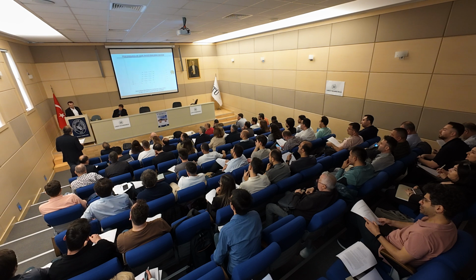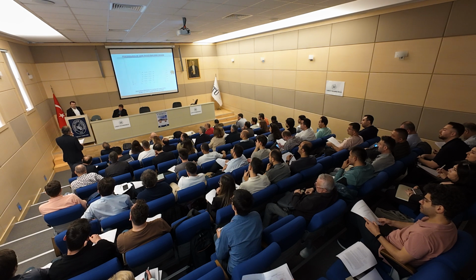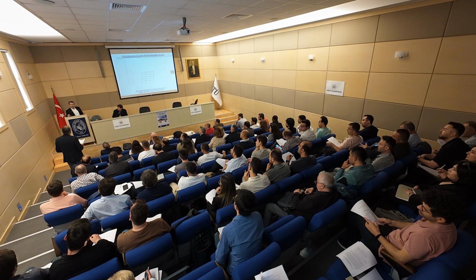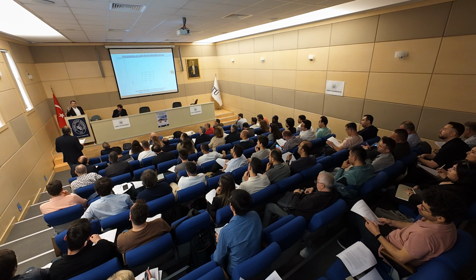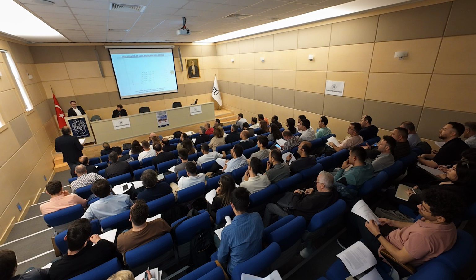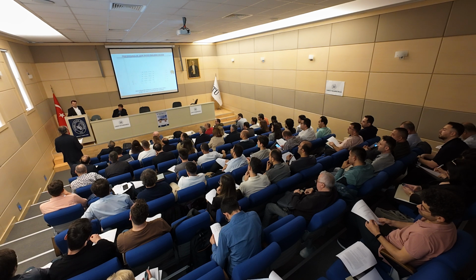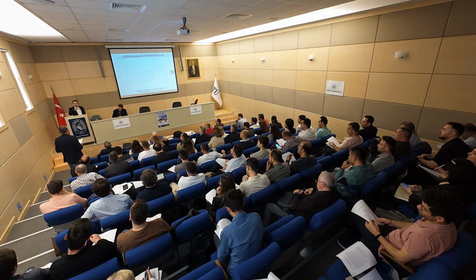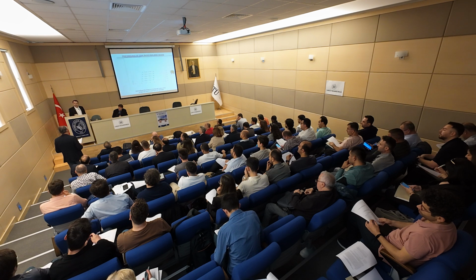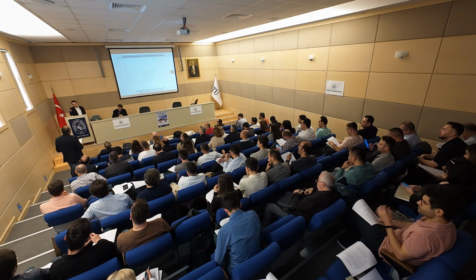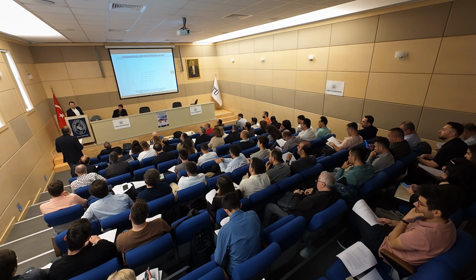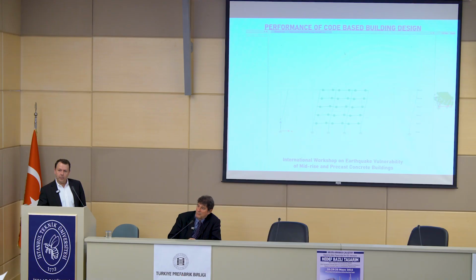Do you have the gravity members in the model? In this model, no. So we would have to check the deformation compatibility. You could add all the gravity members to the model as well. That's why I asked, because you have the chance to have plastic hinging in the gravity members. Yes, and we have to check, both from a moment curvature analysis of the section, or you put it into the model and model the hinges as well. My last question is, are you considering the P-delta effects as you're lowering your drifts? Yes, P-delta always on.